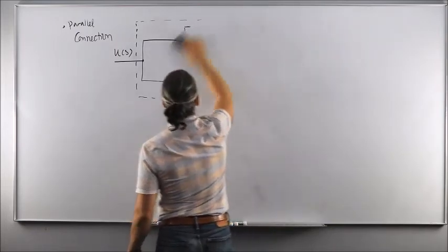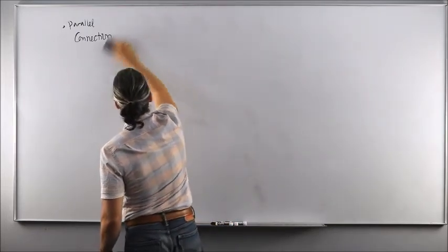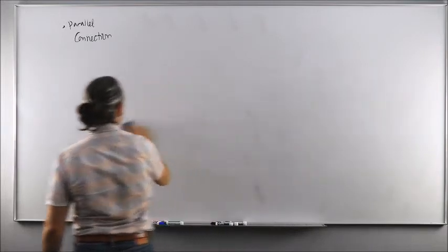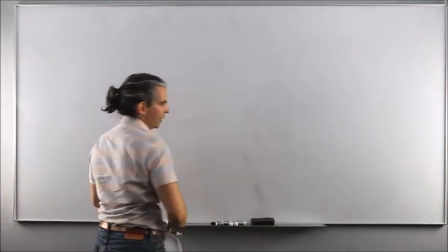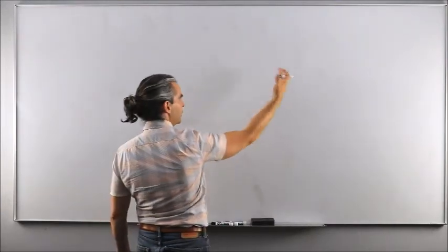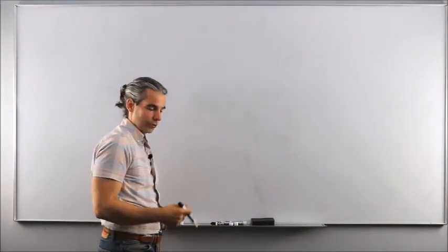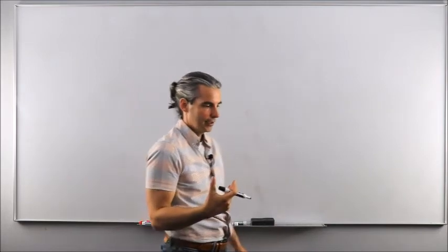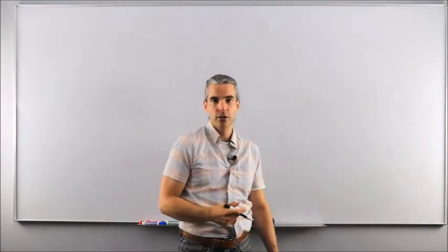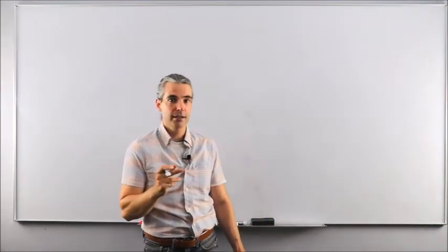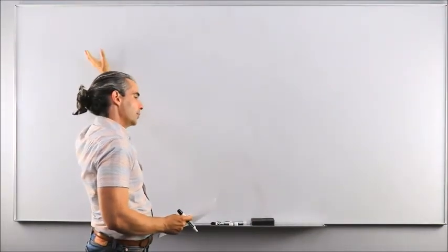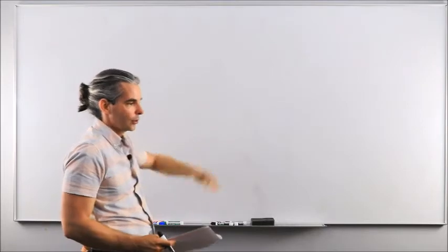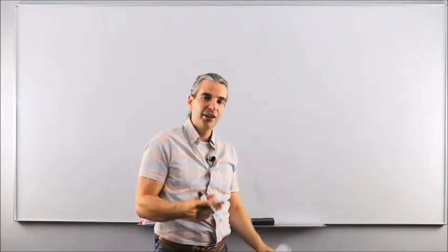And that would be super useful to know how to simplify a block scheme diagram into only one or two transfer functions at the end of the day to do the mapping between the plant output, which would be, in our case, the current rotational angle of the spacecraft about a single axis, and the global input of everything, which would be the user's provided desired angle.